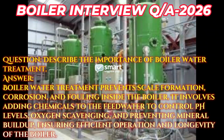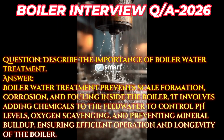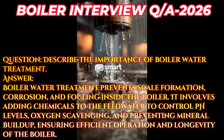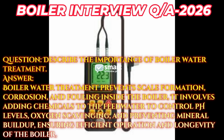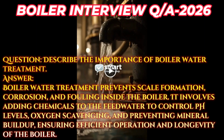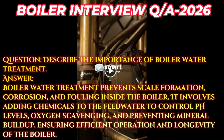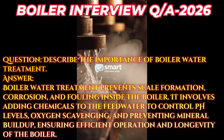Question: describe the importance of boiler water treatment. Answer: boiler water treatment prevents scale formation, corrosion, and fouling inside the boiler. It involves adding chemicals to the feed water to control pH levels, oxygen scavenging, and preventing mineral buildup, ensuring efficient operation and longevity of the boiler.